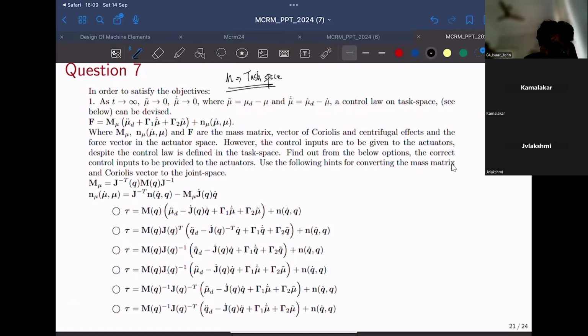Okay, because that makes sense, because as an operator, it's much more convenient to lay down these objectives in task space, because then we'll be able to know how the tip of our end effector would be moving. We can actually visualize that, but it's not very easy to define these objectives from joint space, because to move the end effector from one point to another, we cannot really visualize how the joint space is going to look like. It's much more intuitive to visualize how the task space would be moving.